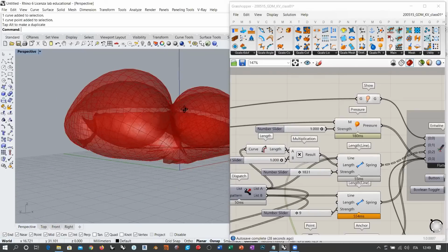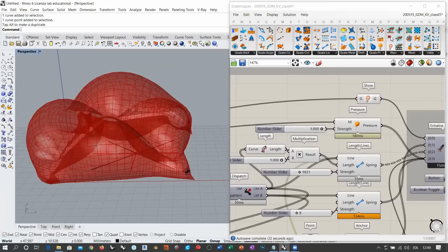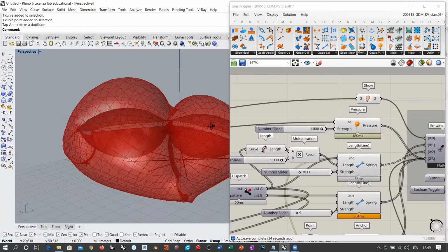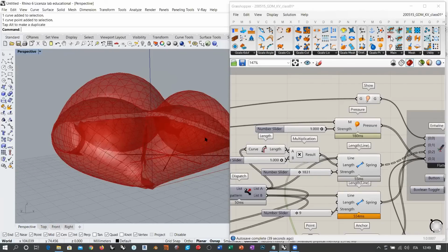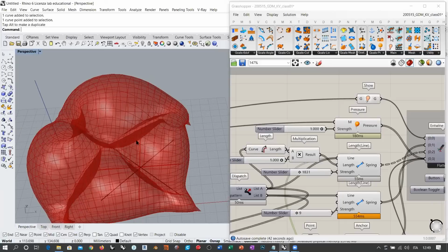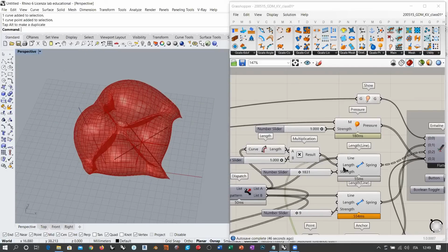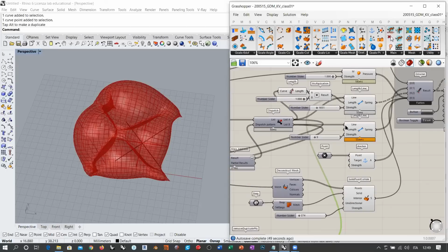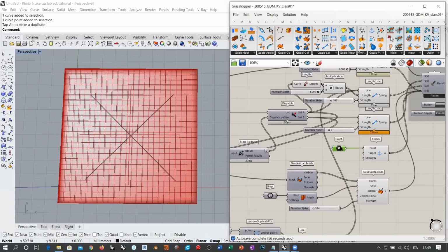You would eventually anchor more points on the corner, because one single vertex, you see, is not enough to keep this mesh under control, especially in this area. You see, this is producing some kind of asymmetric tension inside the object, which is something you don't want, because of the symmetry of the original system. So in this case, you might want to simulate a more efficient anchor situation, which is not just these 4 points here. You might want to take, for example,